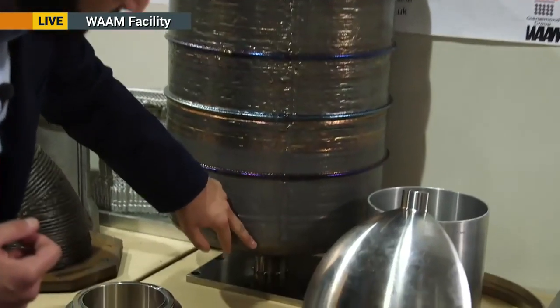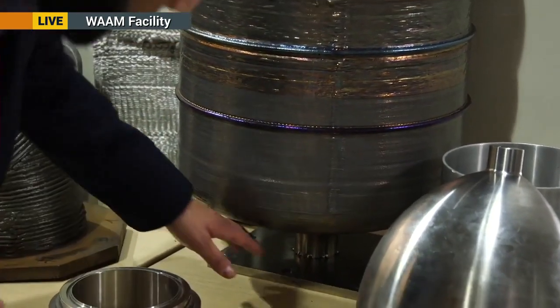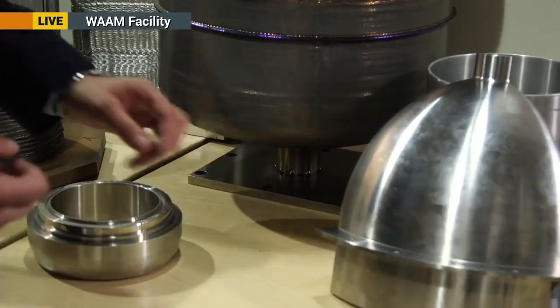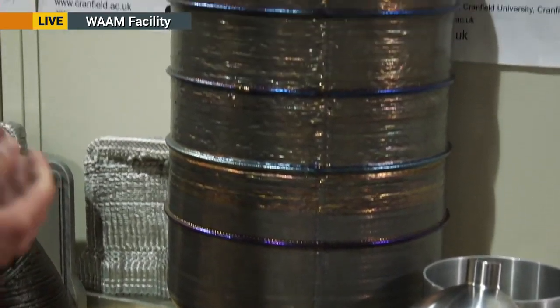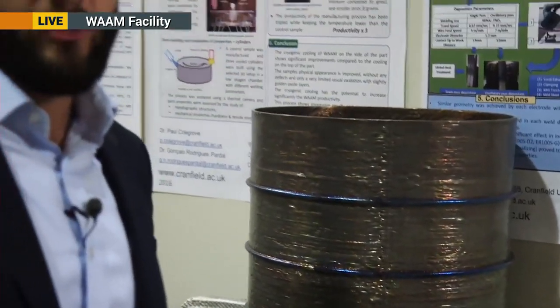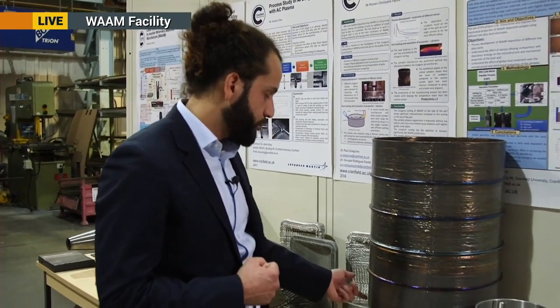Then you've got the bottom dome, which is machined from a separate billet. And then here you would have a conduit, which is where the fluid is drawn out from. Instead, again, by maximizing the manufacturing capability of additive, we've decided to start from a commercially available rod, really easy to get hold of. That's our substrate. We then printed on it the dome, and then we continue with the deposition of the actual main body of the cylinder.